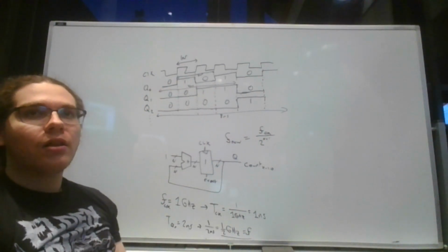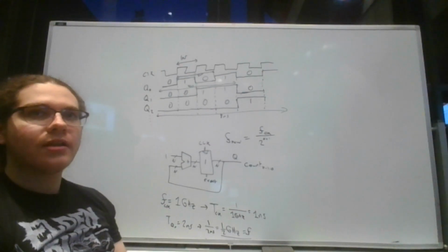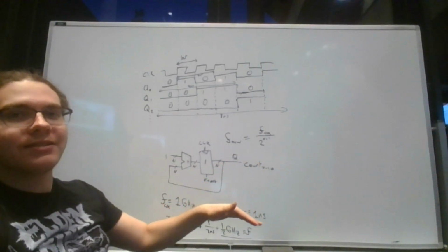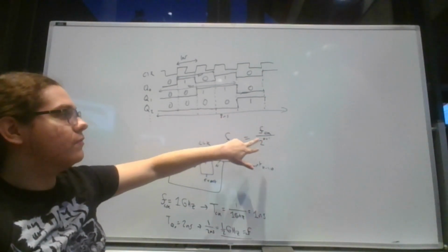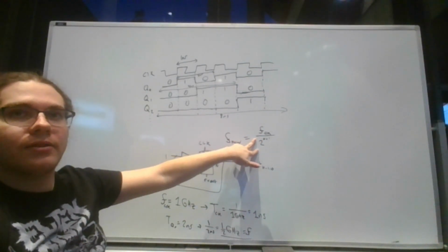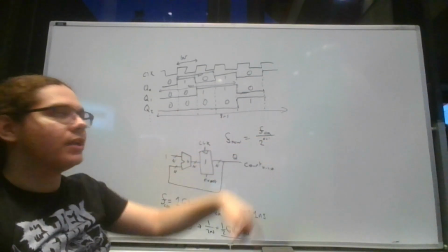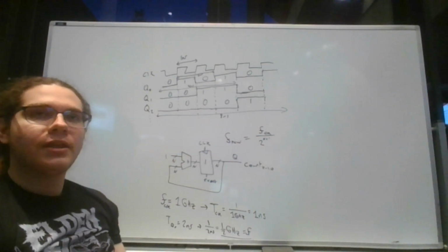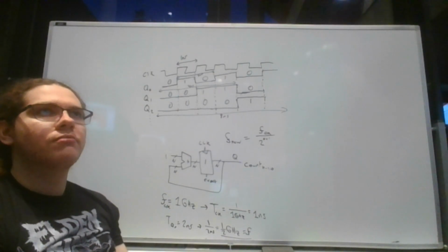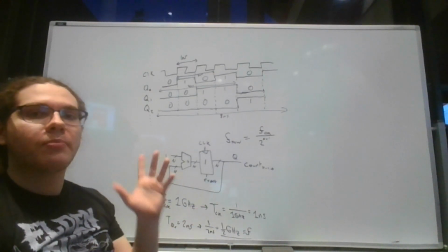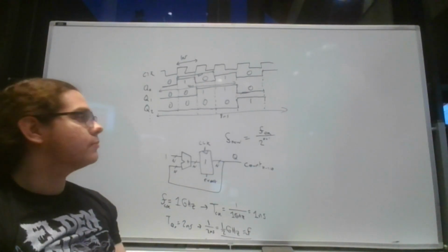And if I wanted a clock that was, say, 1 hertz, I would just have to figure out how many bits down I need to go until I get 1 gigahertz divided by something that's close to 1 billion. So whatever power I have to put here to get close to 1 billion, that's what I'd have to put. And that would be around 2 to the 30, because 2 to the 30 is about 1 billion. So it'd be right around there.